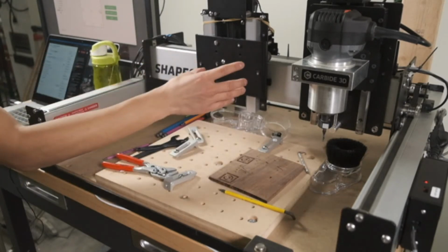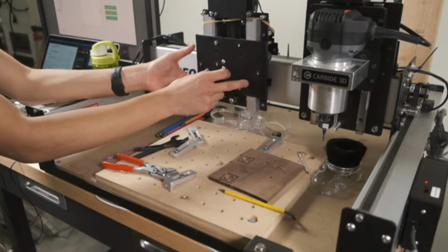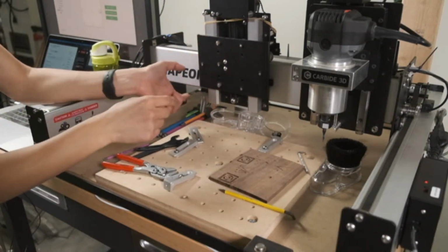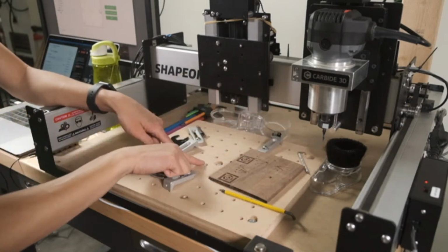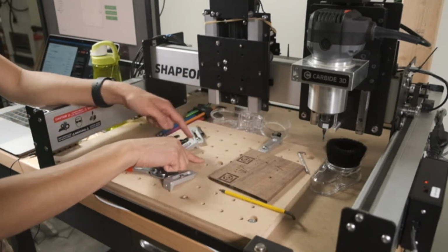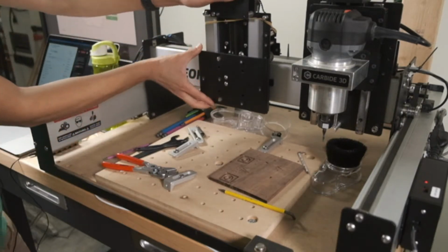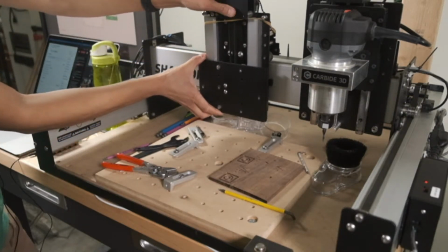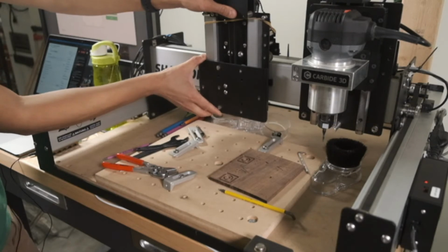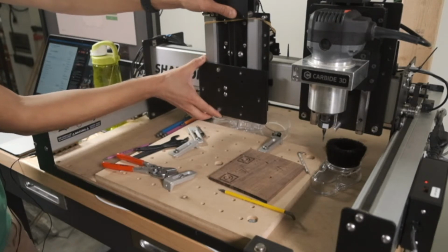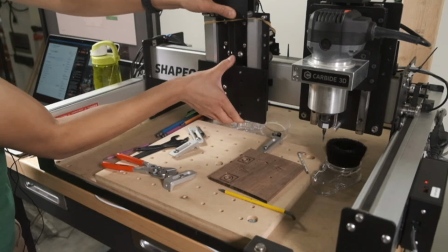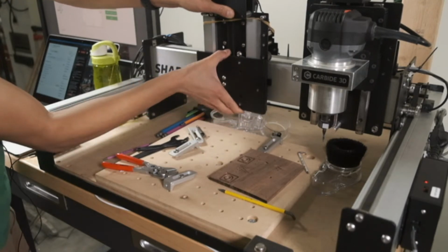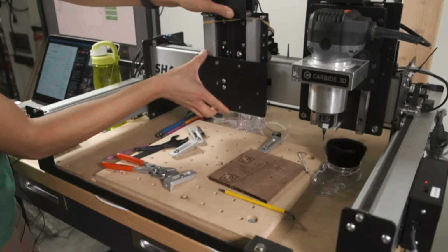So when you have a spindle mounted here, you should always do a check to make sure that your router with the bit can reach the bottom surface of whatever it is you're cutting. Because if this plate comes off, if the bottom wheels come off a little bit, you can develop a little rattling. If they come off even more, you're just swinging freely. And unless you enable soft limits, there's no way to automatically stop this from happening.